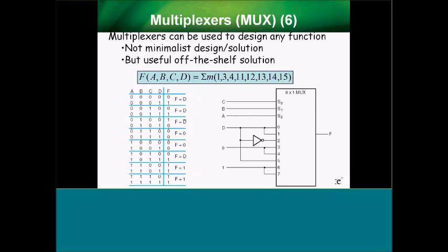Here's one that can be done with an 8x1. Okay, so you have an 8x1 mux. I have 3 select lines. The chart breaks itself up. If you break into 8 pieces, you'll see that ABC just go 0, 0, 0 to 1, 1, 1. So those are your select lines. Then I can bring all the data in on D. And so then it's either D, D prime, 0, or 1. And so the problem breaks out like this. Students respond to this pretty well.